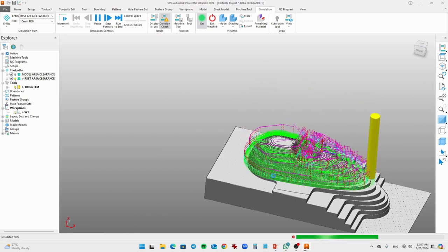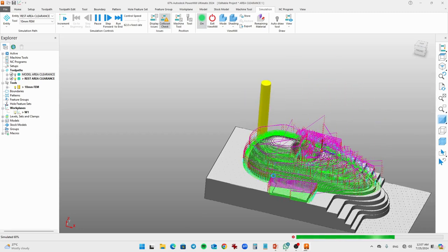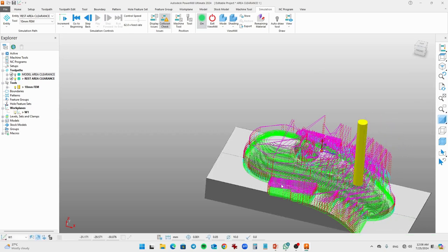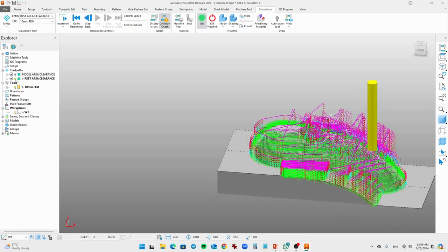So the first thing you have to do is the roughing operation and remove the material in a large amount. Then use the rest area machining to remove the remaining material. And after that, you have to apply the finishing toolpath strategy on this model to give a finishing look to the stock. Okay, so all these three toolpath strategies give you easy access to get your model done in a proper way, and also decrease the machining time. Okay, so this is how it actually works and looks.